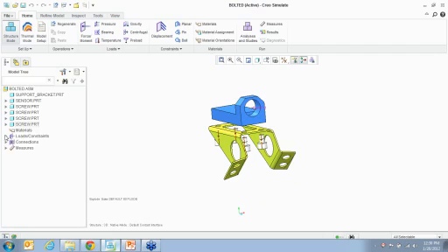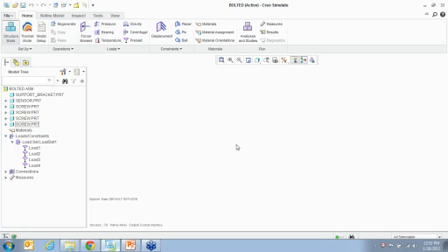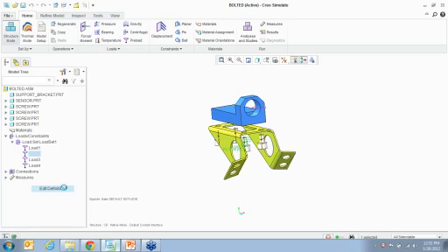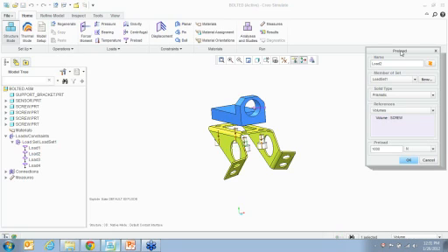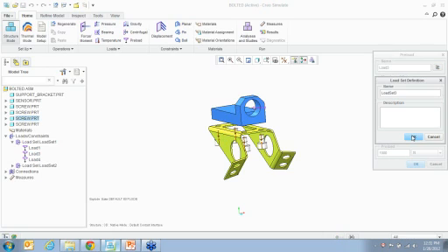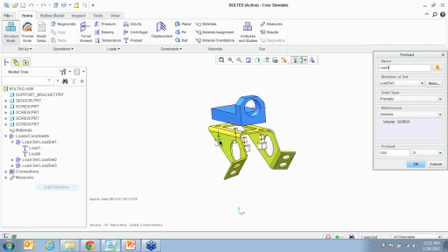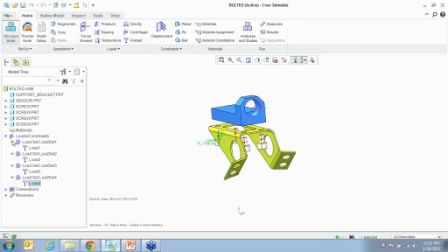Now note that I want to simulate when I tighten the bolt, it is going to compress the part, and I need to know what kind of stresses are induced in the part because of that. Because I put all the bolts in one load set, it's like I'm trying to tighten all the bolts at once, which is not realistic. Maybe there's a robot which does that. But if I'm going to do it manually, first I do this, second I do this, and third and fourth, I might want to put them in different sets. So I'm just adding a new set for each load. That's all it is. So I just added 4 different load sets so that I can apply each load set at different times.